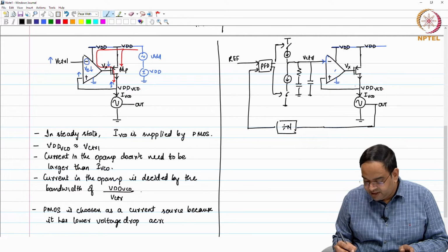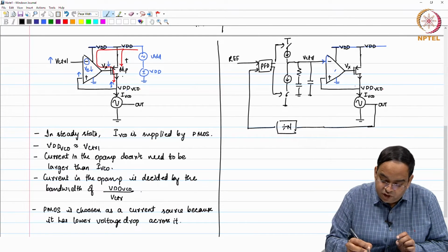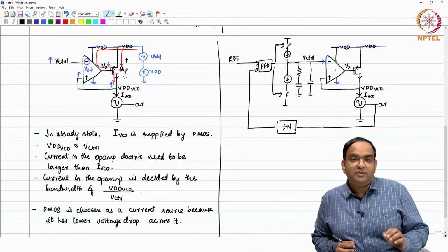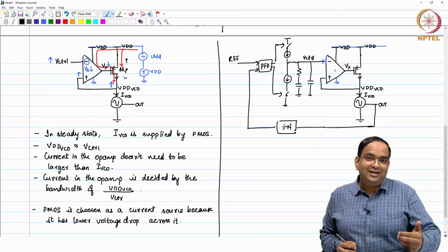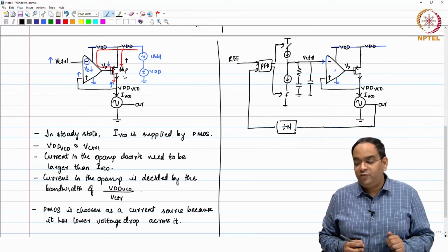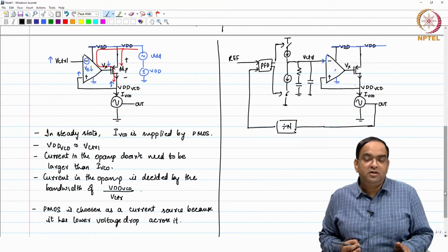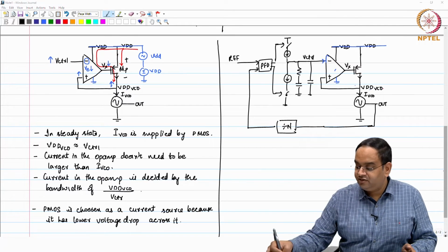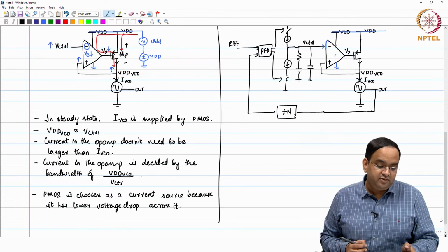And how does it help? Well, if you have a lower voltage drop across PMOS, then it means under a given supply voltage VDD, your VDD VCO can actually be larger, and you can have a larger output frequency. Okay. So, that is what you do in place of Nmos, though Nmos offers a better supply noise rejection, because of this you prefer Pmos sometimes.